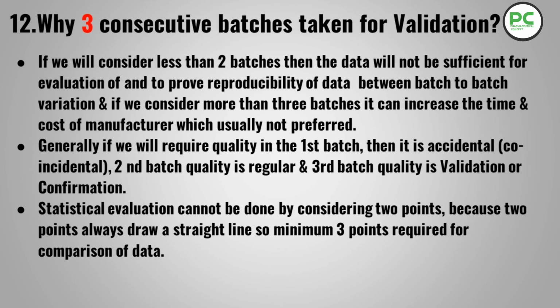If we consider fewer than 3 batches, the data will not be sufficient for evaluation to prove reproducible data and batch to batch variation, and if we consider more than 3 batches, it may increase the time and cost of manufacturing, which is usually not preferred.